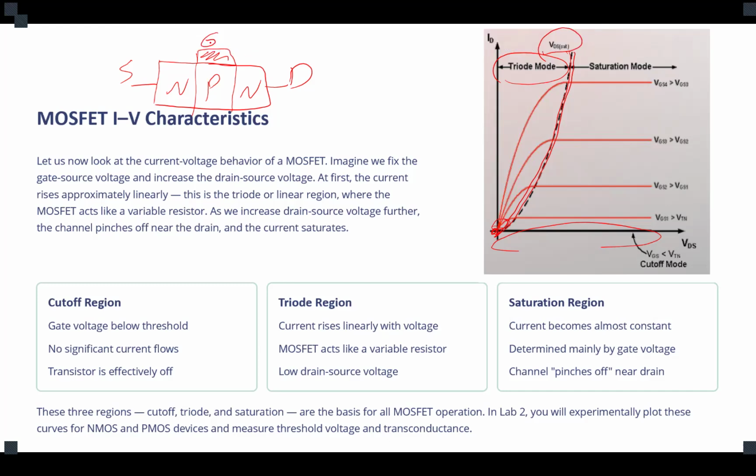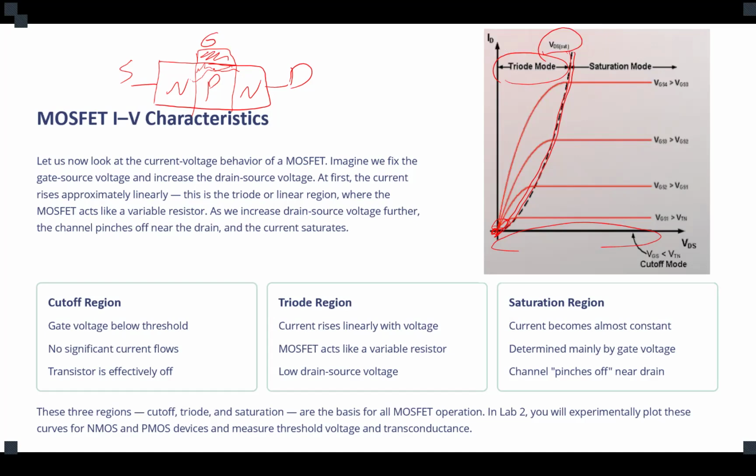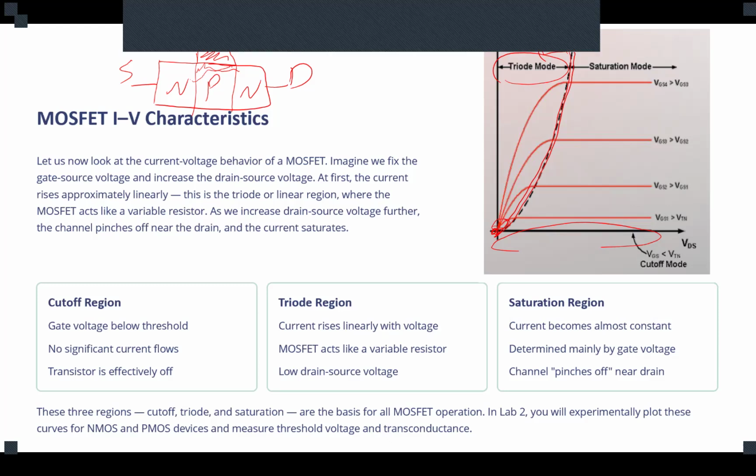Same as what we said about the diode, now it starts to get polarized. So we are going to have a channel that the charges can jump through from source to drain or drain to source. Are we clear? For each specific voltage between gate and source, you would have a certain width of channel.